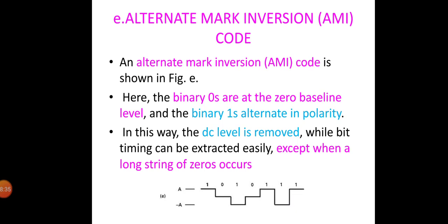For satellite transmission, the encoded message must be modulated onto the microwave carrier. Before examining the modulation process, we describe the way in which speech signals are converted into a digital format through pulse code modulation. So, let us move on to pulse code modulation. The information was assumed to be encoded into one of the digital forms, but speech and video appear naturally as analog signals, and these must be converted into digital form for transmission over a digital link. For example, the speech and video analog signals are shown converted to digital form through the use of A to D converters. The particular form of A to D conversion is known as pulse code modulation.